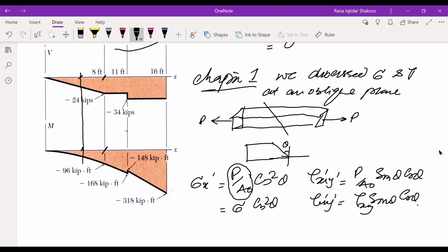These are basically the angular transformation, because theta is there, sines and cosines are there, so we can calculate the amount of normal stress as well as shear stress that changes with respect to any particular angle theta, right? But this is only sigma x, if you remember.